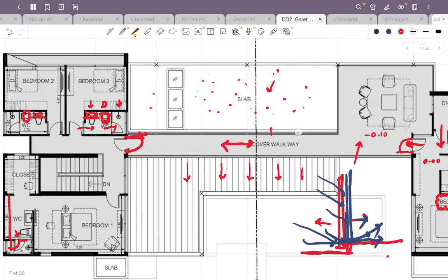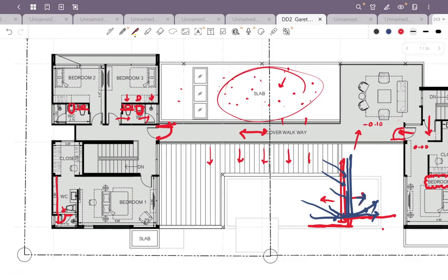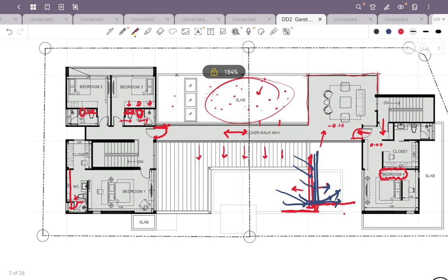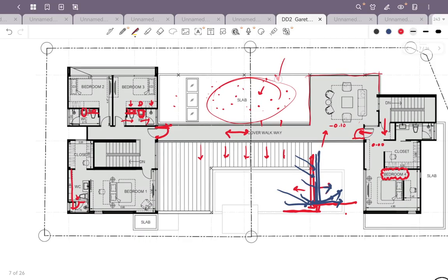And then you also don't have access to use the space when you have already paid for the whole structure, for the floor. You should use this for the terrace or something, but look, it's very big here. I'm not sure, right now you have the terrace here already. For me, I think the house can be compact and use the flat slab space for the second floor function. You will save money if you design the layout. Now, if you can revise the layout.